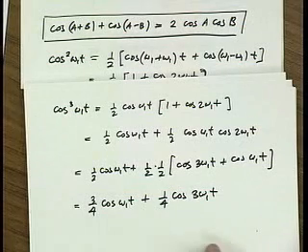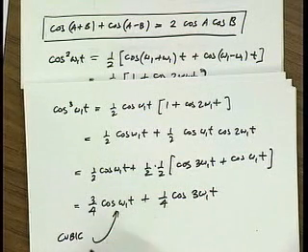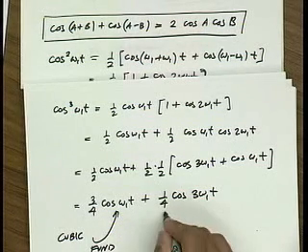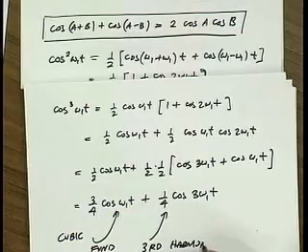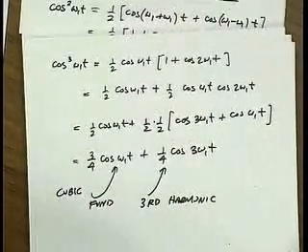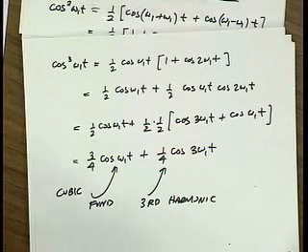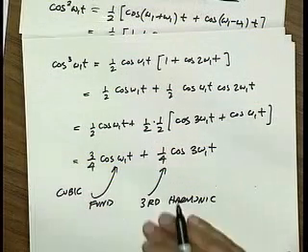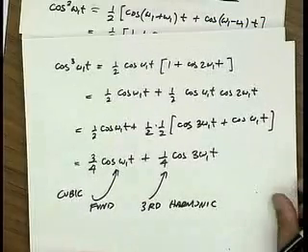Okay? And so we see that cubic will generate fundamental and it will generate third harmonic. And last lecture, what we proved was more generally that any even power will generate even harmonics, right, including DC, and any odd power will generate all odd harmonics, including starting from the fundamental. Okay, so that's a quick recap from last lecture.